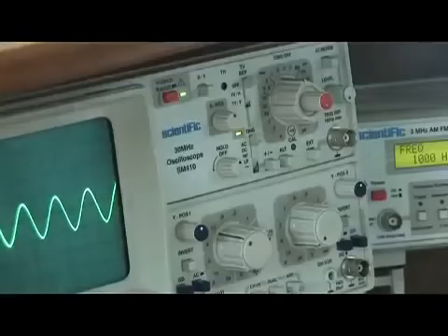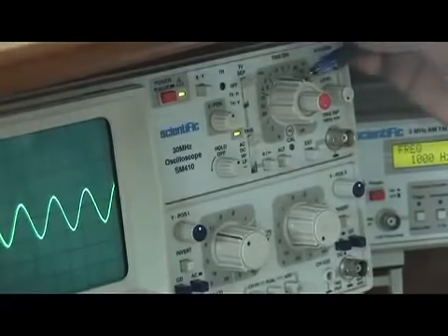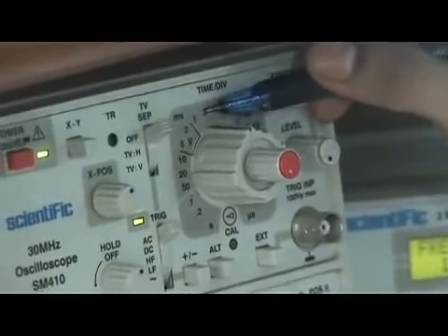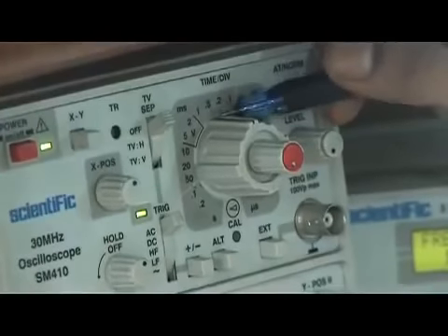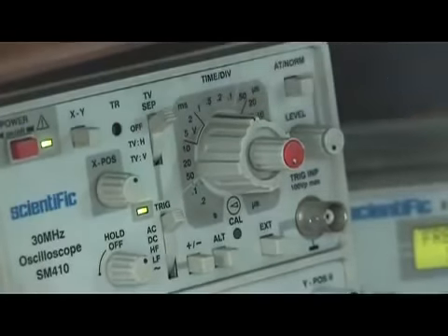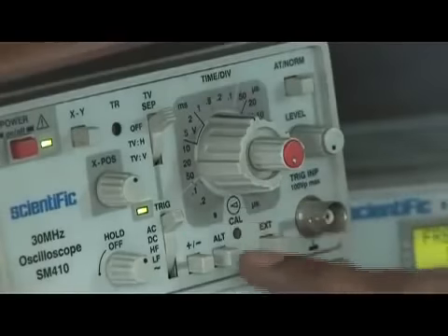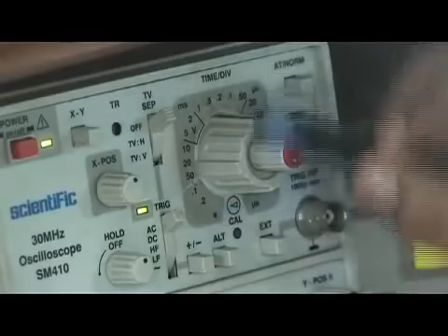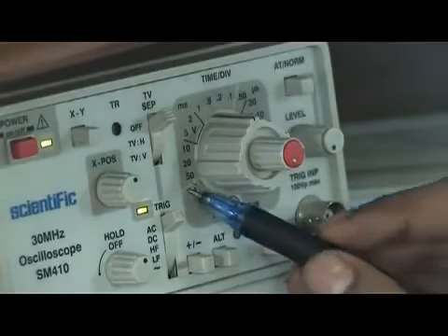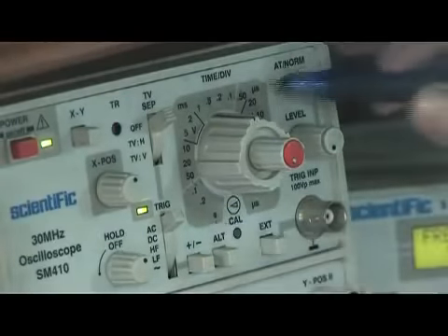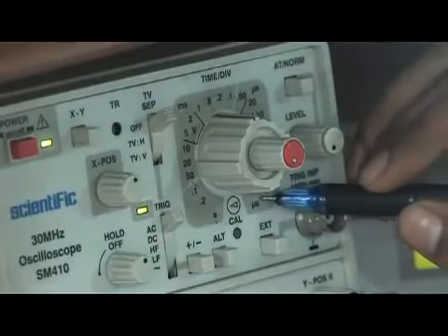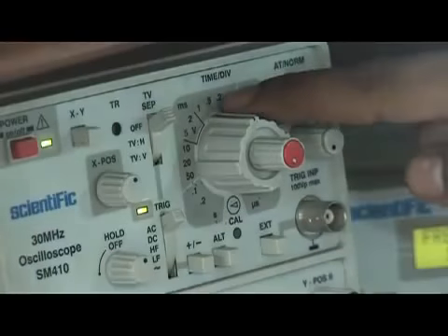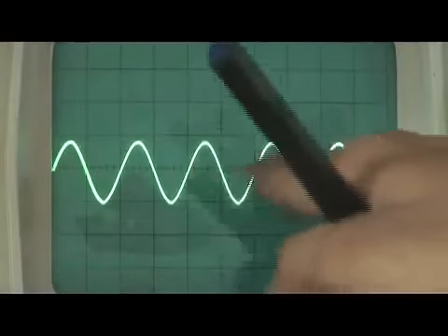So it is 2 into, where you can see this knob lies, there is a line, this one, it lies at 0.5. So 2 into 0.5 is how much? 2 into 0.5 is 1. So 1, what will be the unit? From this gap till this small gap, you can see here, between these the unit will be in milliseconds. From this gap to here, the unit will be in seconds. From this gap till here, the unit will be in microseconds. But right now we are in the range of milliseconds. That's why 2 into 0.5 milliseconds. What we got is the time period.